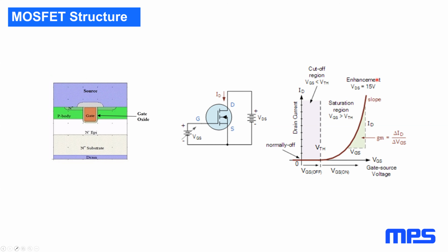That's up here. In switching applications, like most power applications, we're mostly concerned with two states, fully off and fully on. So we focus on driving the gate terminal quickly from the cutoff region with no current flow to the linear region, which is fully turned on. However, there are some reasons why we might want to slow down that transition, and we'll talk a bit more about that later.